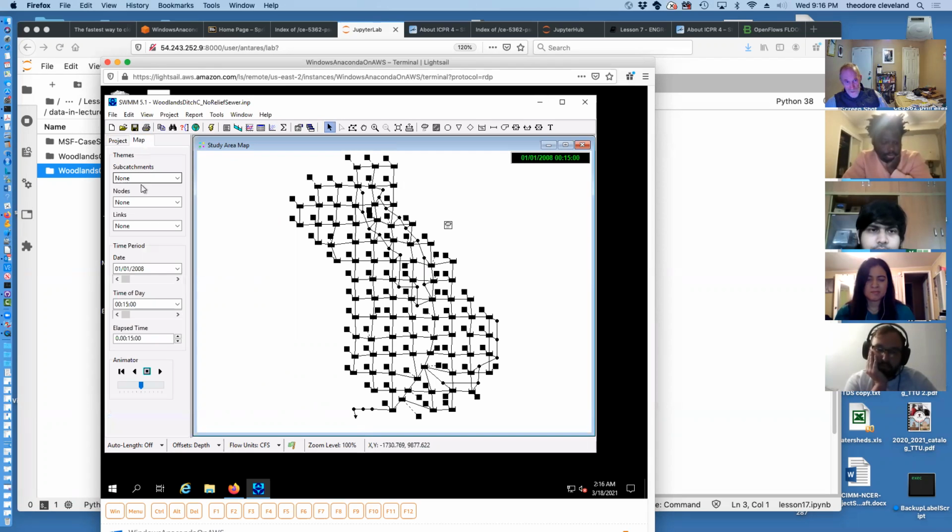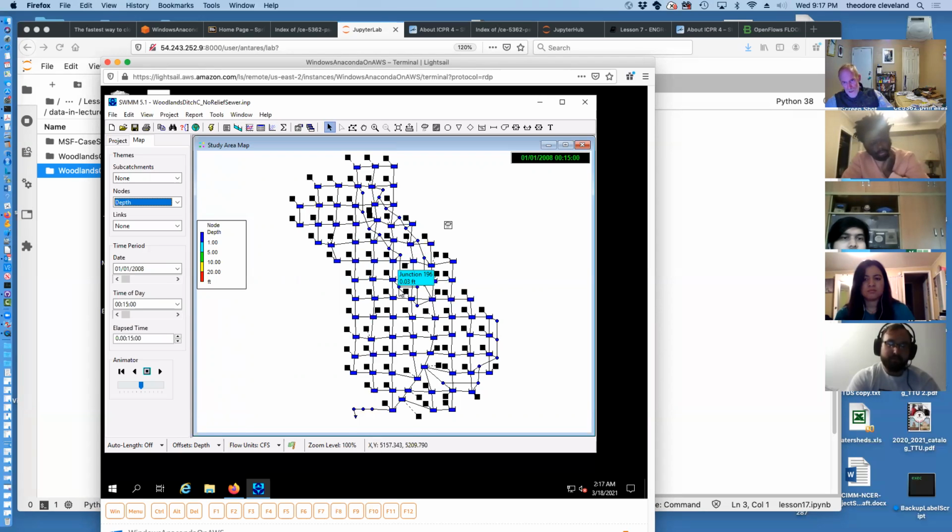Let's go ahead and use the map. We're going to take the nodes. We're going to put flow depth, and this is a non-routine coloring scheme. So I suspect that a flow depth of anything over 1 foot, we'll see that as a color change. And if the flow depth gets over 20 feet, we'll get red. Now keep in mind, these sewers are underground at least 10 feet. So these don't become a concern until we get red values in the surface nodes.